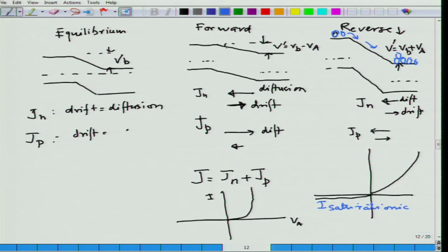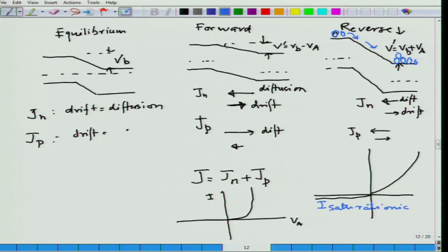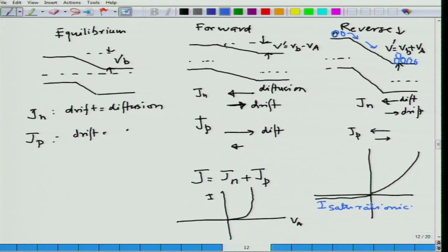And so, in this sense we have a simple p-n junction. We just used a material, and because of the property of the material, it develops a built in potential. Now, we apply a voltage to it. If I apply positive voltage, I get a huge current, and this is because the built in potential gets reduced. If I apply reverse bias, I have more bias and the current substantially gets reduced, and that is almost a very small amount of saturation current in there. And this is basically your diode.